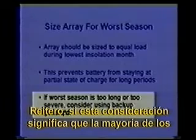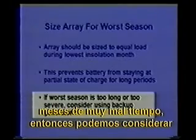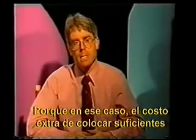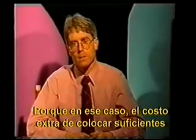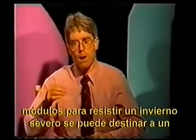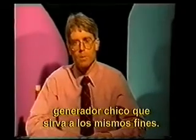Again, if this consideration means that most of the months we could operate from photovoltaics, but there might be a few months of extremely bad weather, then we might consider using a hybrid system or a generator. Because in that case, the extra cost involved in putting in modules to get us through that severely bad winter is not spent. Instead, we spend it on a small generator that can get us through that small period of bad weather.